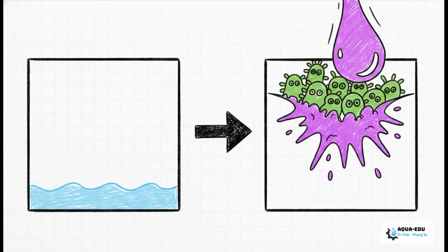But hey, sometimes it's on us, right? If you, as the operator, let the equalization tank drop way too low, you've completely lost your buffer volume. Without that massive volume of water to dilute an incoming spike, the shock goes straight to the bugs in the aeration tank with devastating concentration. Poor level management can literally turn a minor spill into a major plant shutdown.